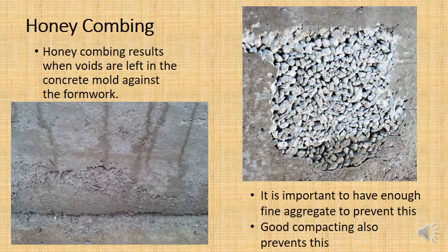You can see honeycombing on both those pictures. You've probably seen honeycombing at various places where concrete has been used to make structures, and it's very bad. Normally, if there's honeycombing to that extent, the civil engineer shouldn't approve it, and it needs to be redone, unless, of course, it's not actually structurally important to the integrity of the infrastructure.